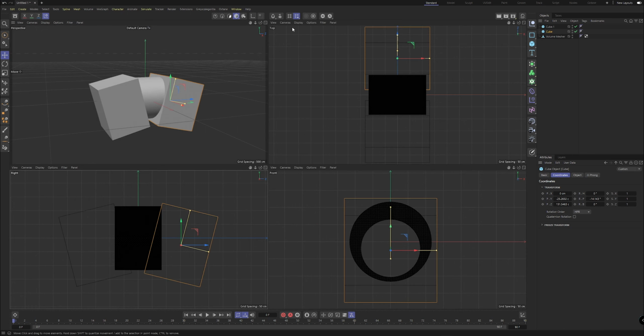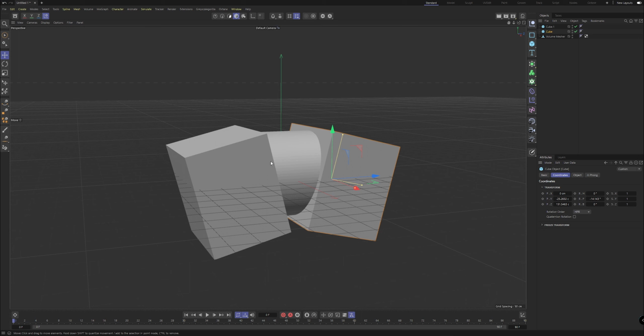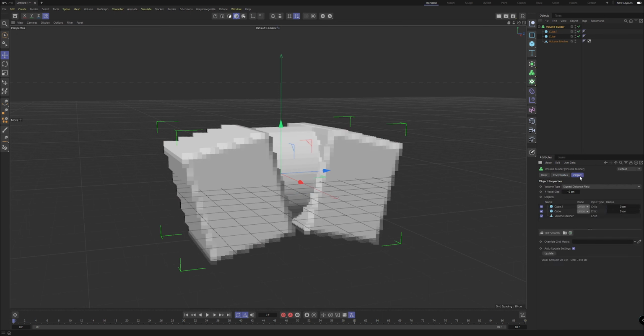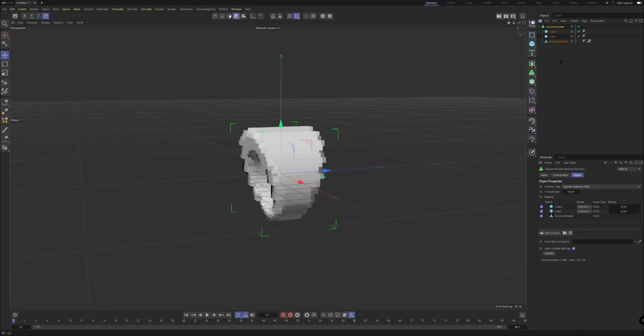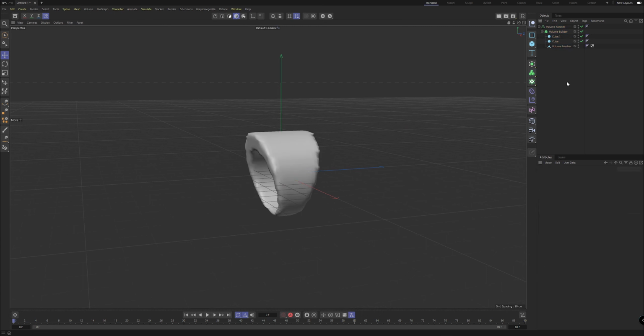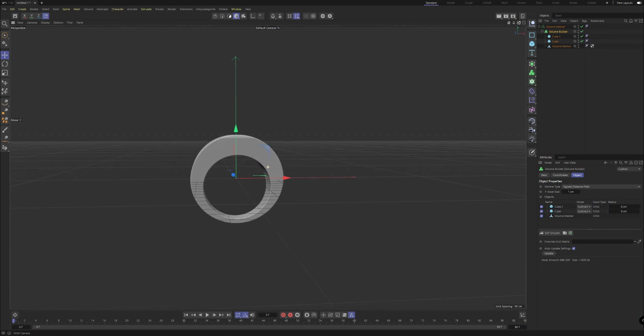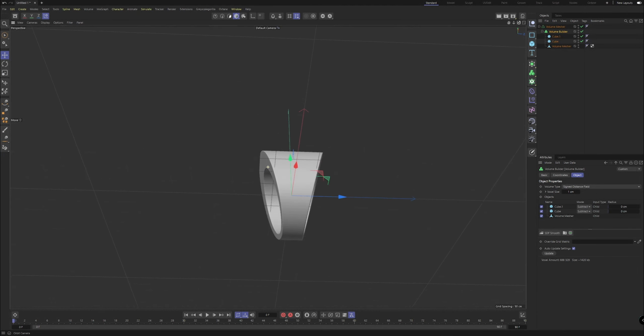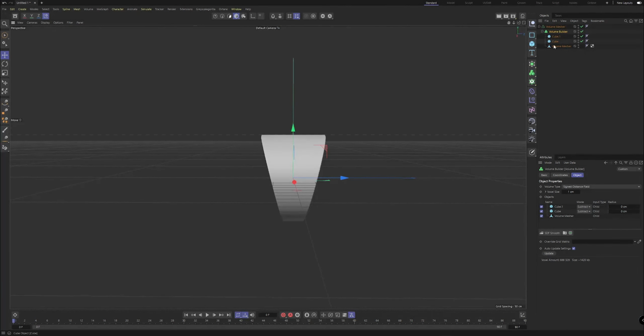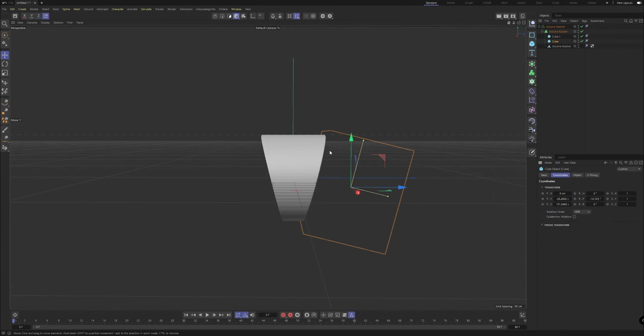So now what we can do is, you're seeing it's going to take this original geometry and subtract these boxes from it, right? So we can knock these into volume builder and subtract both these cubes, and then drag it into a volume measure, and we can tweak this if need be. But we want to decrease our voxel size real quick, so we're working with as much detail as we can for now. As you start decreasing the detail, you start getting some weird shapes here and there. But this looks pretty good. Don't worry about how sharp it looks for now, because there's a load of smoothing techniques you can use. So that is something we can fix later on.